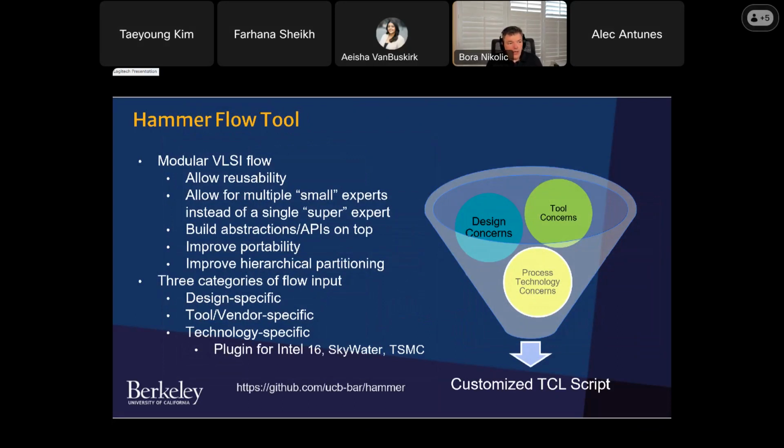When we have the RTL, students in research and in teaching need to take that RTL and translate it to GDS. Usually when you work in a company or in a university, people will try to put together a tool flow that invokes a number of tools that do synthesis, place and route, and other collateral steps that translate that RTL, written in Verilog or VHDL, down to a correct layout that is LVS and DRC clean.